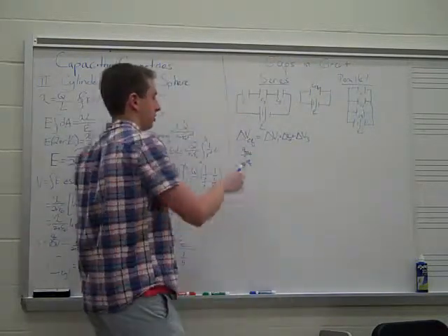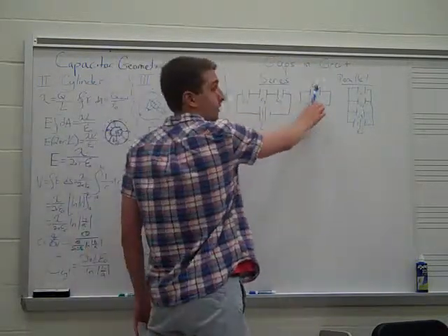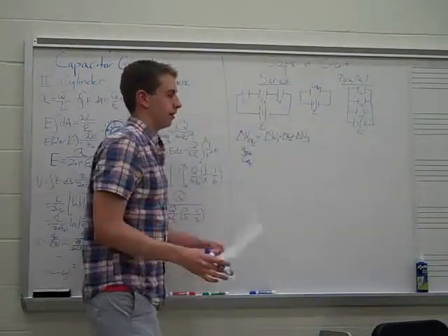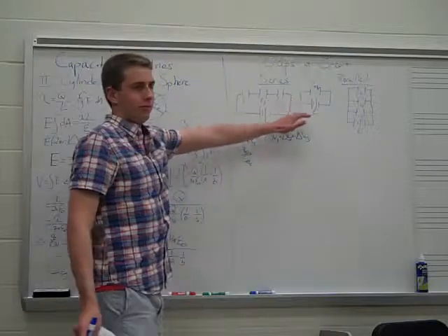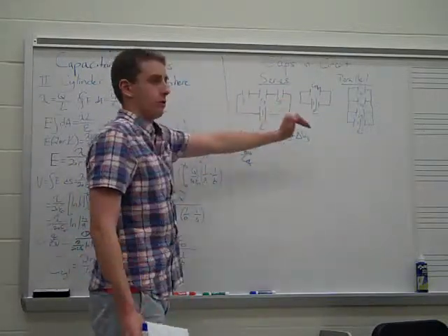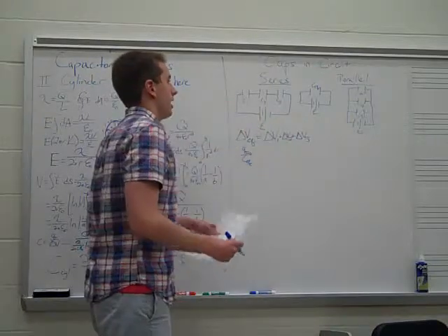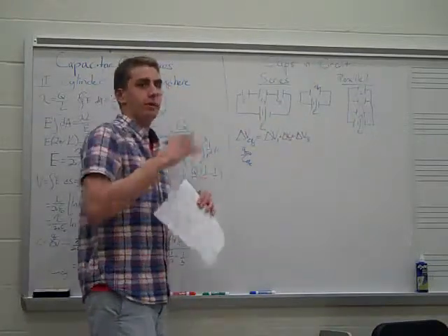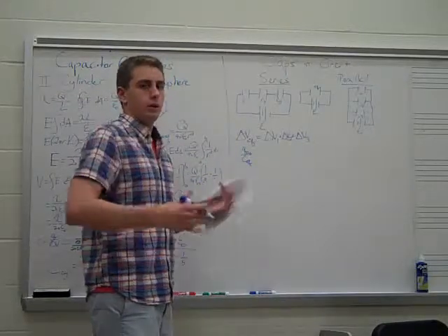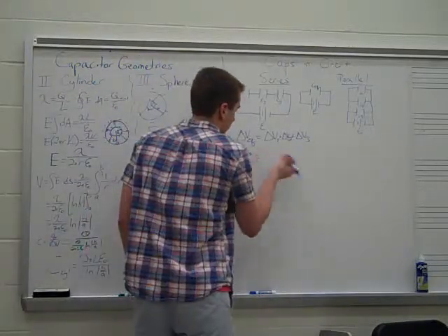And we know that the Q on all of these must equal each other, and must equal the Q on the equivalent circuit, because they're all experiencing the same current. So we're not going to get a certain percentage of the charge. We're going to get the same amount of charge once all caps are fully charged.